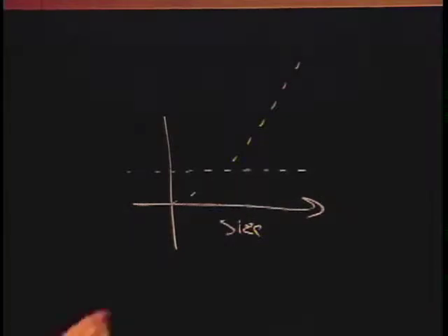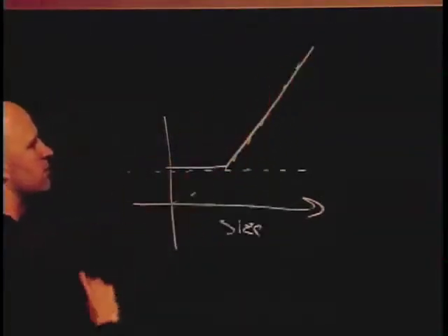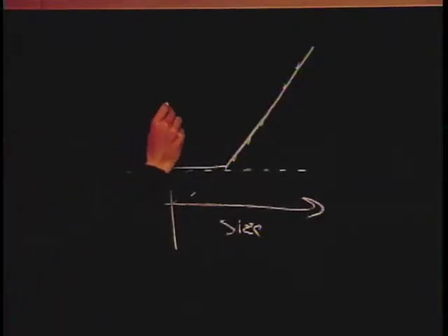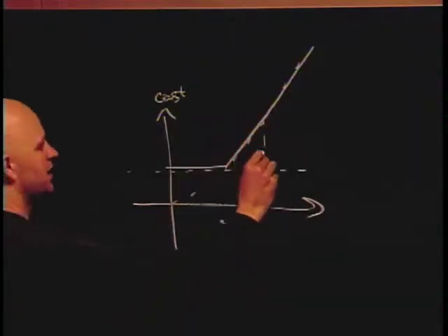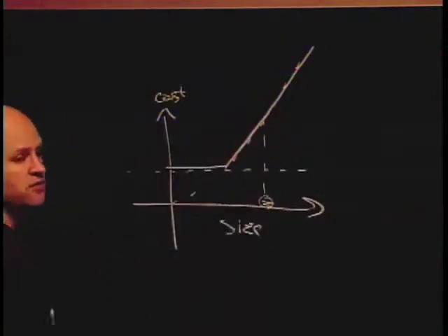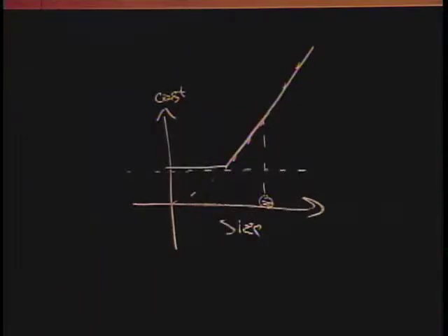What does this say as far as the cost? Size versus cost. This graph makes sense, right? This is kind of how we'd think of how expensive it would be to rasterize a triangle. Well, when you're NVIDIA and you build a hardware rasterizer, you have to pick one particular place on this curve and say, we're going to build the rasterizer for that. We know that that point right now is about 8 pixels per triangle. That might be the crossover point you find, for instance. They designed for that point.